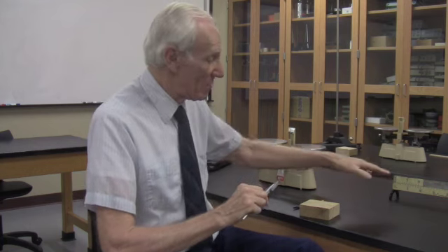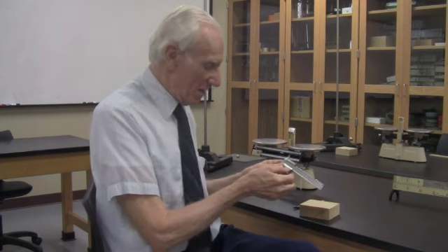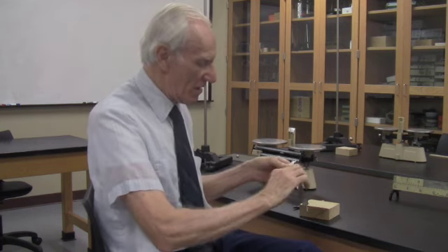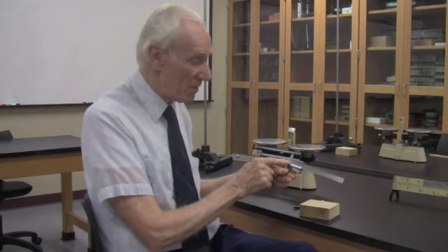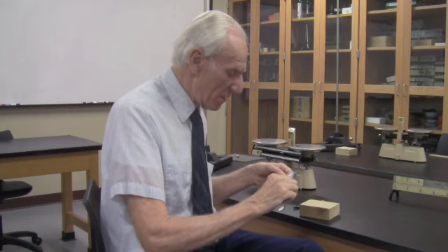So this caliper is a little more accurate than the scale that we have here. It's accurate to, according to the very fine writing on the sliding scale, again, the index mark is at the 0 of the sliding scale, it says 0.02 millimeters, which means it's theoretically accurate to not a tenth of a millimeter, but 0.02 millimeters, which is 5 times more accurate than even if you didn't have to guess on the meter stick. So it's like 20 times theoretically more accurate than reading and estimating that last digit on the meter stick.